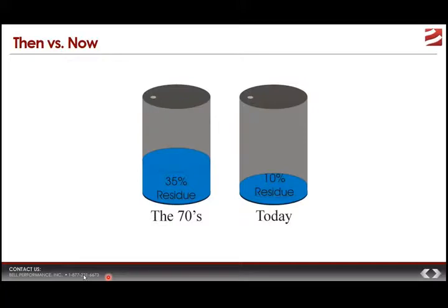Now, gasoline and diesel fuel, the number one and number two diesels, those are considered distillate fuels, whereas the heavier things, the things that are left over, essentially, when those things are taken off, things like heavy fuel oil, those kinds of things are classified as residuals. Now, historically, as you can see from the graphic, you go back to, let's say, the early 1970s, typically you would get between 52 and 65% of the crude oil would come off as distillates. Now, this says 35% residue, which means 65% distillate.